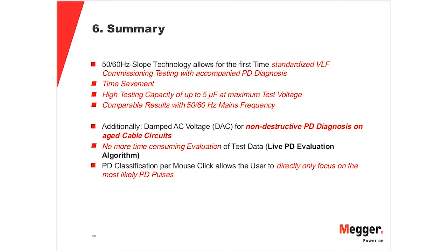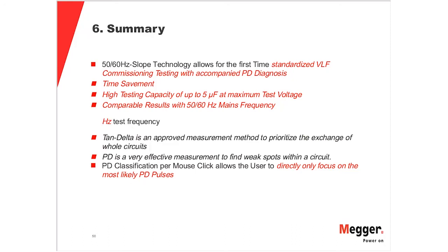In addition to that, we also have the so-called DAC technology, which is a non-destructive test, which is mainly recommended to be used on your aged circuit, where you are worried that this test might fail if you apply 1.5 or 3 times your nominal voltage. Also very important, there is no expertise required from you. The expert is delivered with the system, and the algorithm is automatically identifying and localizing the problems. So you don't need to be a specialist at all. It is already built into the system.